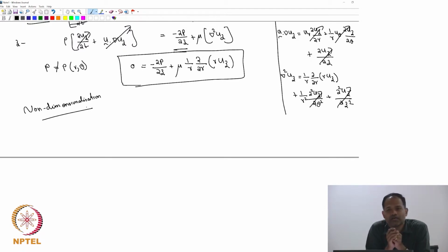So, how do we do that? How can we get rid of the dimensions of velocity? You have to divide it by another quantity which has the units of velocity. So, that is one thing. What is the other quantity that we need to non-dimensionalize? Length, r, radius. See, what are we expecting to see? We are expecting to see uz as a function of r. That is our objective. So, we want to non-dimensionalize our velocity, and we want to non-dimensionalize our length.